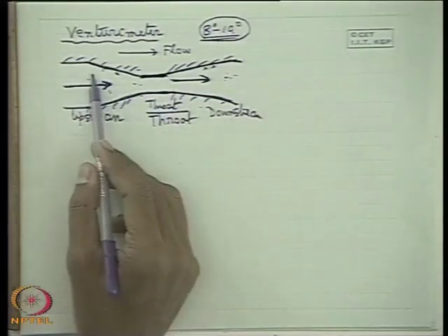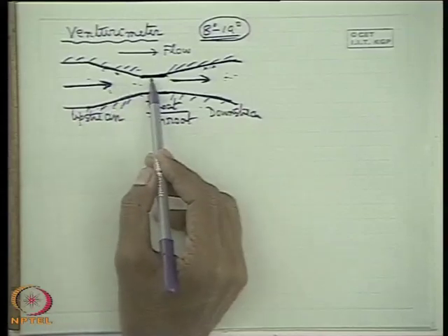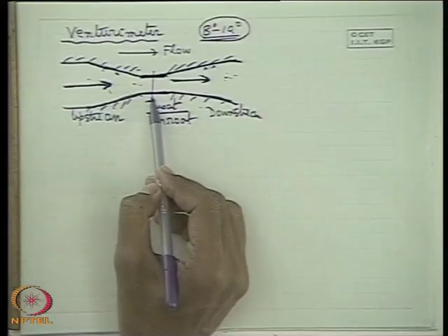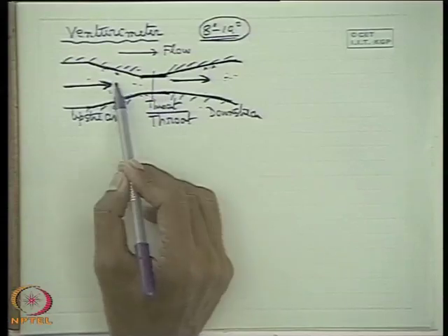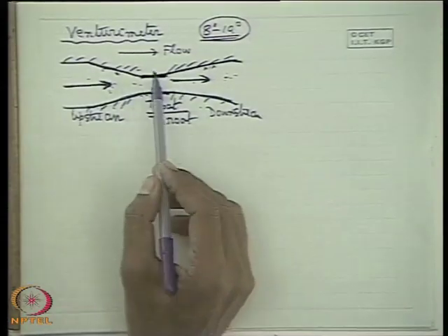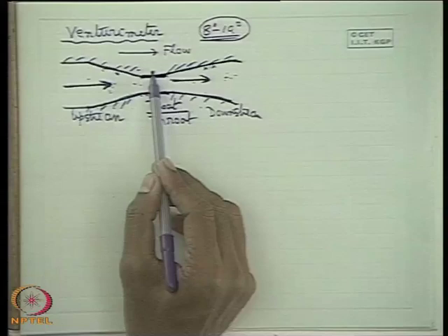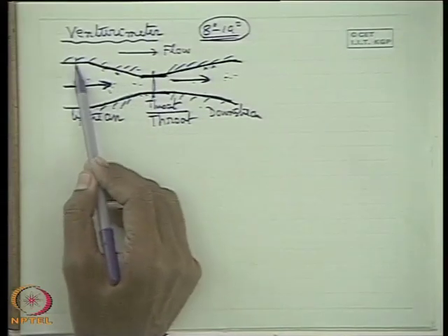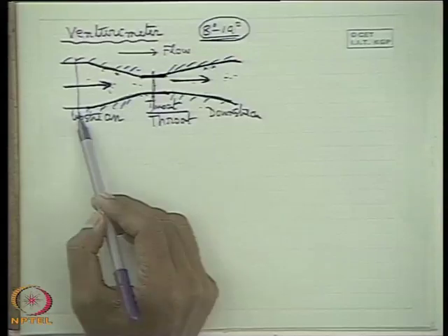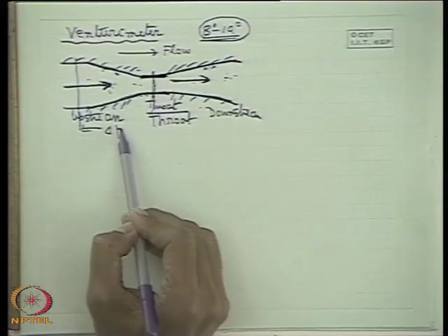Now as the fluid flows through this in this direction, the maximum velocity occurs at the throat. That is the minimum area part. It is a very short straight portion which connects these two conical parts. Similarly, the pressure here is the minimum, velocity here is the maximum. According to continuity, pressure here is the minimum. So if we measure the delta P between these two, there is a pressure difference between these two sections.